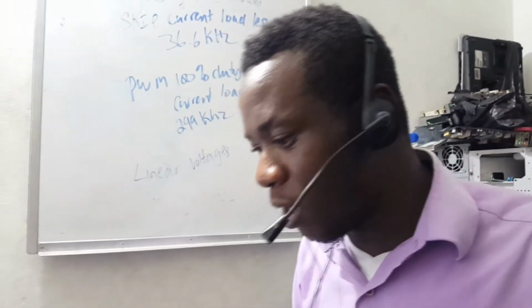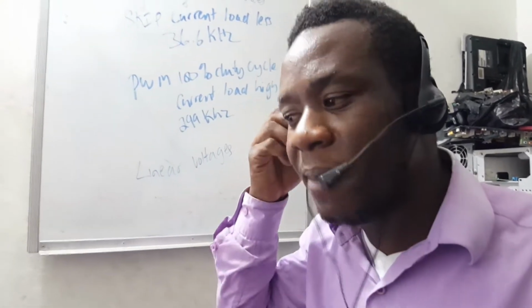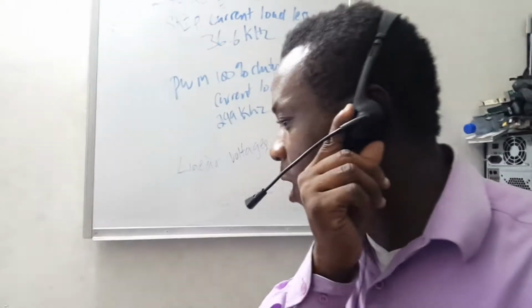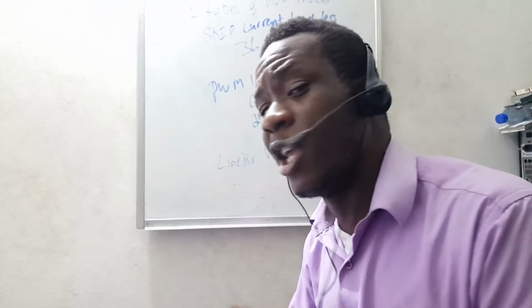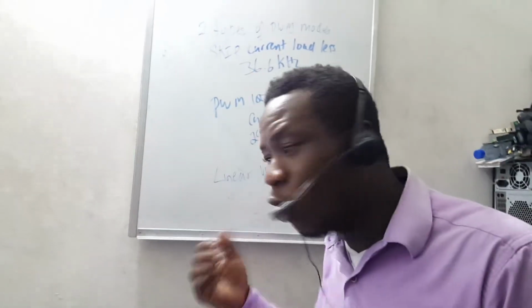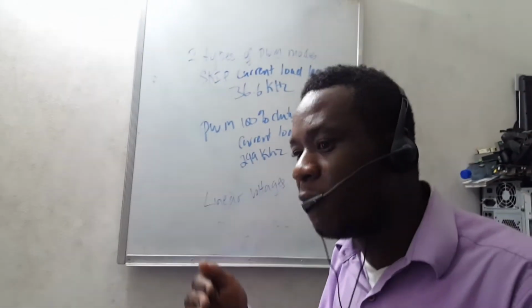And it is a step down because why is it called a step down? Because it's taking it from 19V. Beautiful. So it's taking it from a 19 voltage, from a higher voltage to a lesser voltage, right? So it's a dual step down switch mode power supply controller, generates a logic supply. You know why it's called a logic supply? The output is not fixed, because it is working in an adjustable way. So on one board you might have 3.3V, on the next board you might have 3.4V.